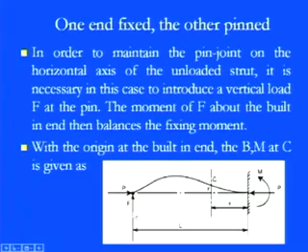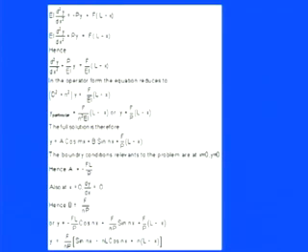The moment can be there due to the external moment M, and also due to the force F. Now with the same standard bending equation, we have EI d2y by dx square equals minus P into y, because of the axial load and the y deflection at point C. Plus, up to point C, the distance x is the main influencing parameter, and as you saw in the previous figure, the vertical load F gives another moment, but the effective distance is L minus x.